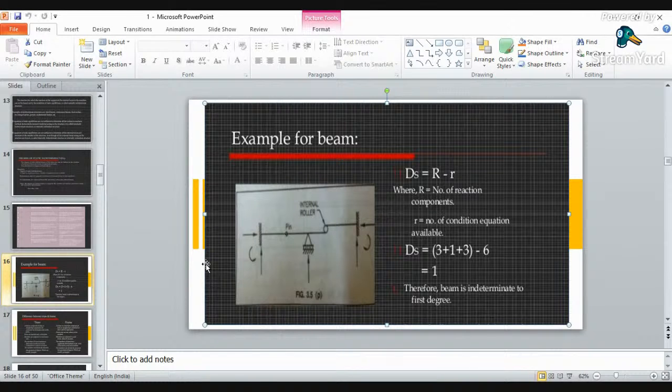Okay, in beam elements we will deal with only two types of structural forces, that is force and moments. And we have three equilibrium conditions. So your beam can be analyzed by using the equilibrium conditions internally. That is why the internal indeterminacy of a beam is equal to 0.